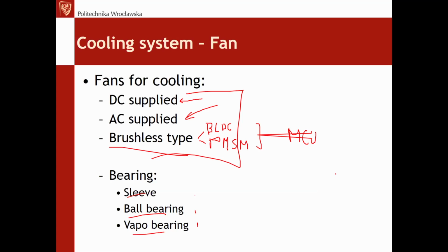Today it's not a problem because we can find small microcontrollers especially designed for brushless motors, for the control of brushless torque and rotation and so on, because a couple of things the microcontroller must measure. So the overall construction is more complex, yet today brushless motors give very high reliability if you are able to cope with the electronics. They have excellent parameters at lower weight and even, I would say, lower price. Overall cost is even lower today.